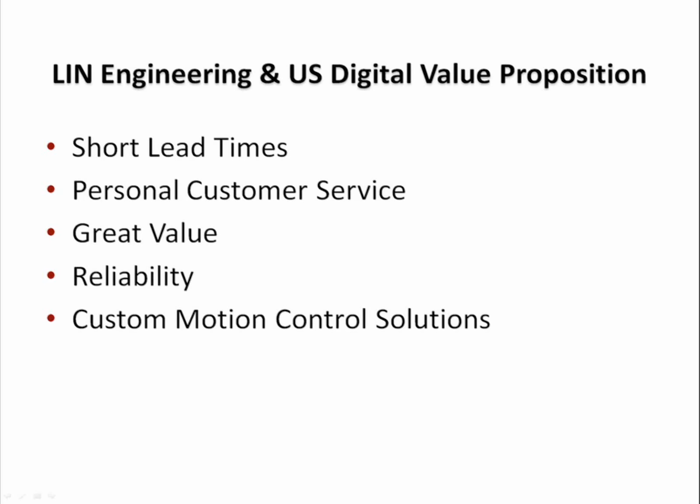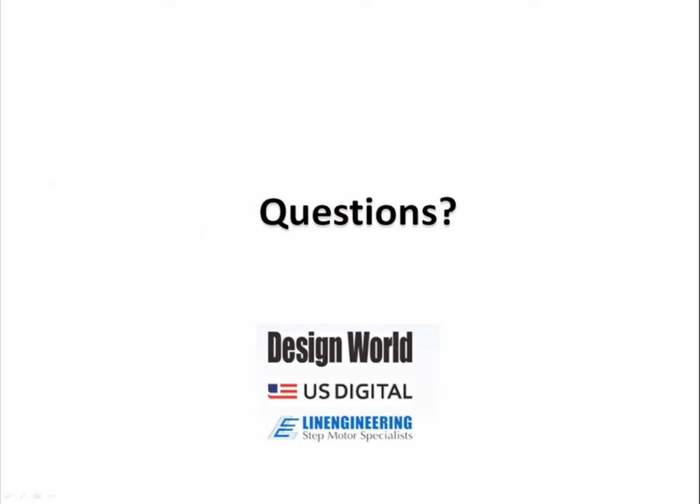Yeah, thanks, Josh. We share similar philosophies, and it couldn't be said better. So there was actually a question that came up during your presentation, which was, can you explain the difference between an encoder and resolver, advantages or disadvantages? Good question. So an encoder provides you direct digital outputs from your application, essentially. Whereas a resolver, if you rip a resolver apart, it looks a lot like a motor. It has windings, and it generates an analog signal, which then has to be converted into a digital format.